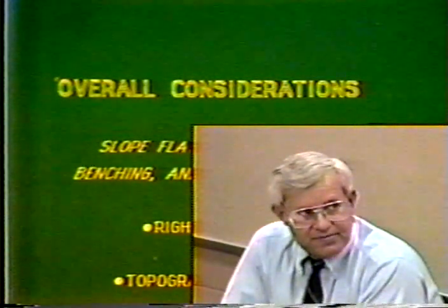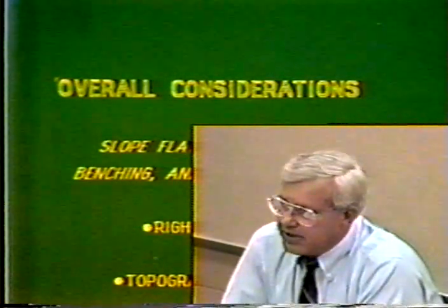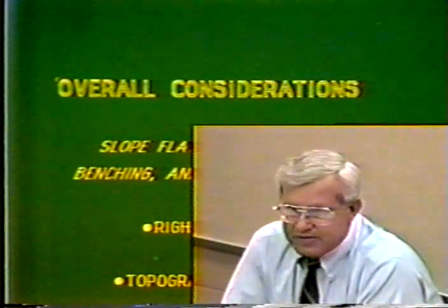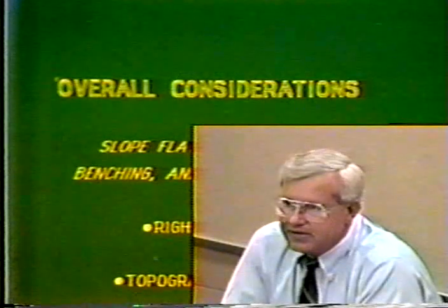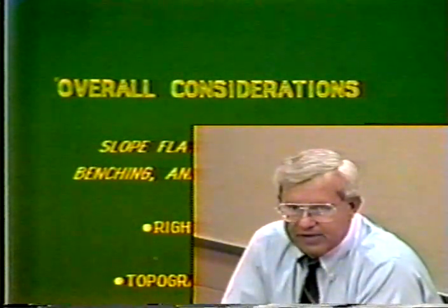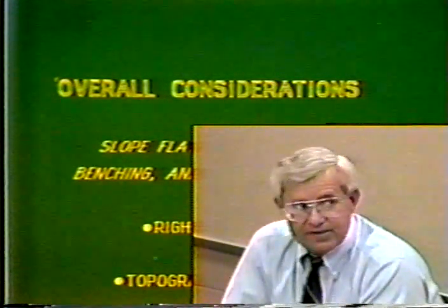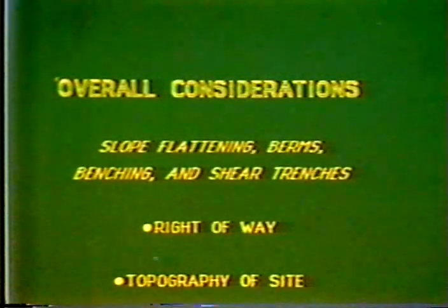One thing you may do is find out where the right-of-way is, because you may have to use slope flattening or a berm or so on. If you've got enough room, you may not have to worry about things, but you need to know the location of that right-of-way at a particular slide. And you can either go to the courthouse or during the spare time. I doubt if maintenance has too much spare time, though, but you can do a little footwork in advance if a section's showing distress. Of course, you've got to be aware of the topography of the site.